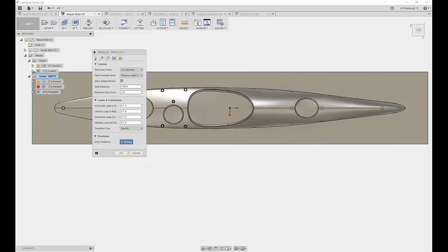And the second point is that a lot of controls will have different kinds of smoothing behavior for rapid moves, and many controls would not really like you to have a lot of motion with G0s or rapid moves. They would cause a lot of stopping and restarting. So in a lot of cases, at least, just high feed G1 moves will actually run smoother on machines.